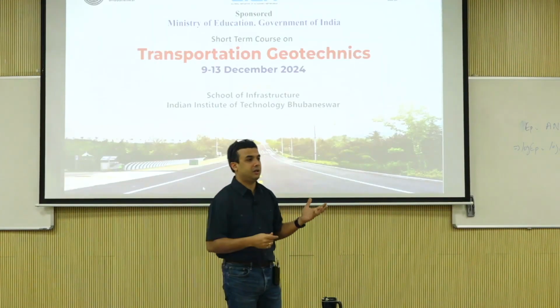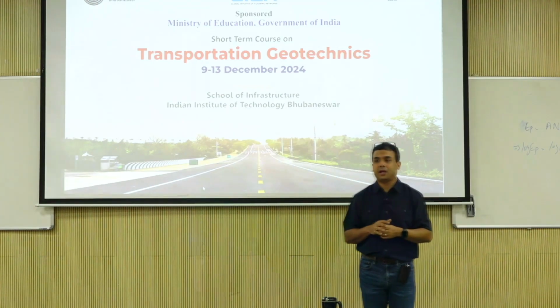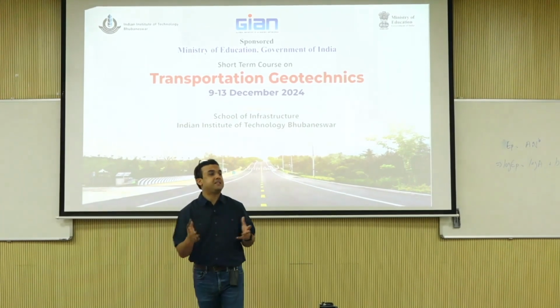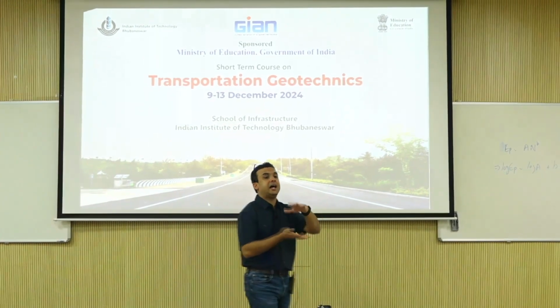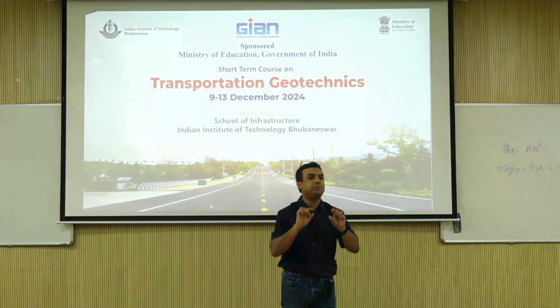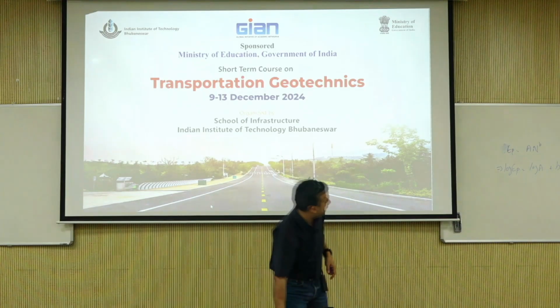It's not a constant number, right? So then the question becomes, how would you take care of stress dependency in a layered elastic formulation or something? Just use sublayers. Just use sublayers, find representative modulus values or find representative stress and then iterate on that. I think I told you this.